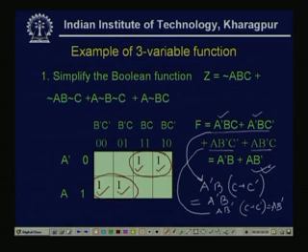Now, from the Karnaugh map I can also directly tell that these 4 terms will be reduced to these 2 terms, because the first couple reduces to a complement, as b is fixed, so a bar b. For the second couple, the second row represents the literal a, and for the first 2 columns, 0 0 and 0 1, it means that b bar is fixed.